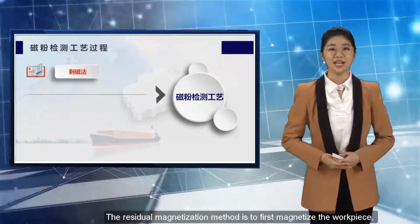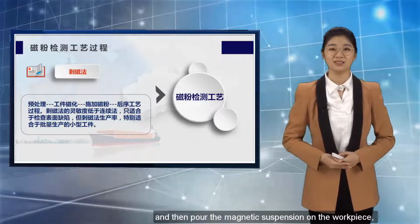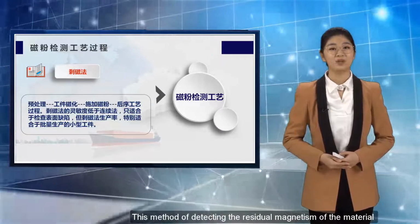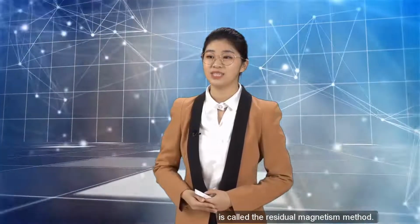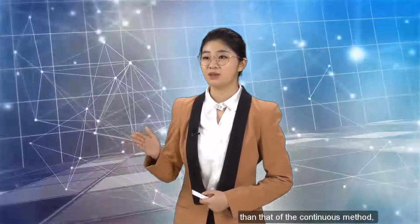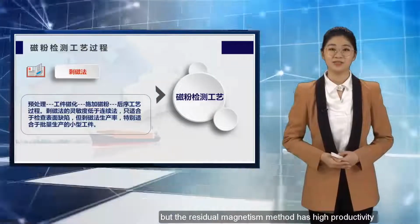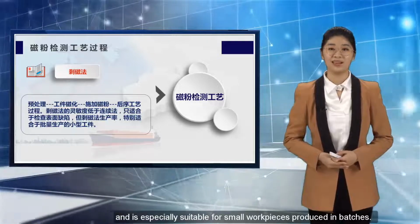The residual magnetization method is to first magnetize the workpiece, and then pour the magnetic suspension on the workpiece, and observe it after the magnetic powder is coagulated. This method of detecting the residual magnetism of the material is called the residual magnetism method. The sensitivity of the residual magnetism method is lower than that of the continuous method, and it is only suitable for inspecting surface defects, but the residual magnetism method has high productivity and is especially suitable for small workpieces produced in batches.